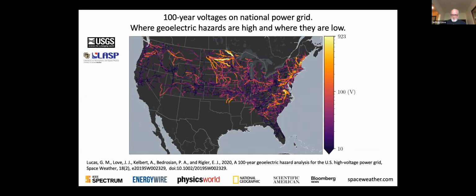That means that the currents you could expect to be induced in the high hazard places can be typically about 2 orders of magnitude higher than in the low hazard areas. So that is an important and large amplitude effect that can be usefully applied to projects which are intended to mitigate power grid hazards experienced during magnetic storms.